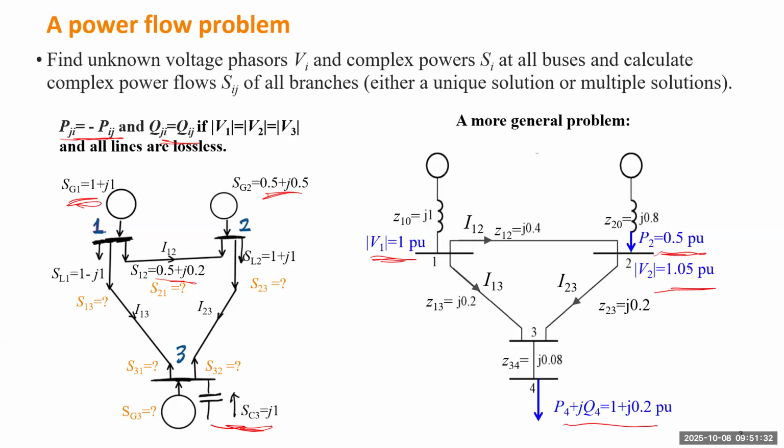This is pretty much a generator. If it's a generator bus, we can control the active power. We'll talk about how to control the active power, or dispatch among multiple generators, in the next session, session number 7, the optimal dispatch session. And for each generator, I can decide what voltage I need to operate at. So I have an exciter or automatic voltage controller, and I can set the setpoint for the voltage. So 1.05 means this generator's terminal voltage will be slightly higher than the base value, about 5% higher. So this can make the generator generate some reactive power for the neighbor buses.